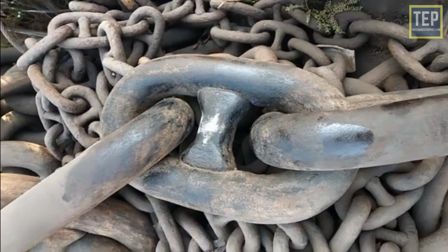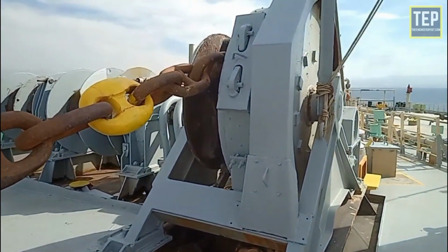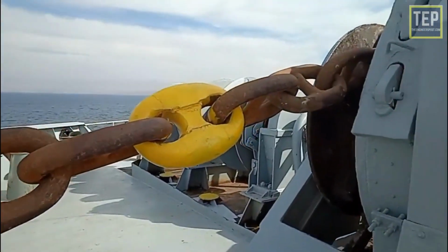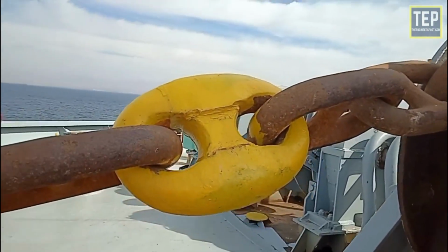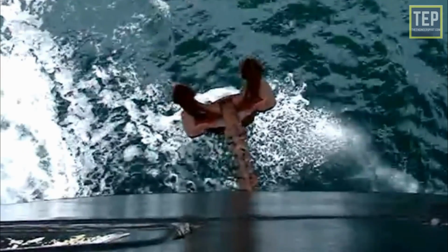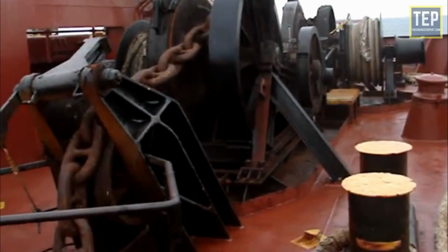The stud link chains are used to minimize the deformation and link easily. In this type of chain, a round bar or stud is used to fit inside the oval link chains to provide them more strength. It is used in ships to raise and lower the anchor of the ships and some crane hoists where we need to lift a very high amount of load.